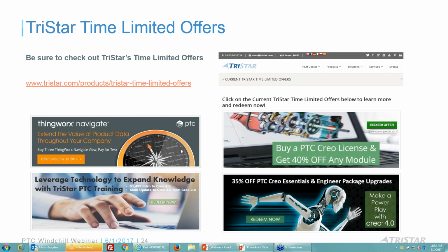Another question was, is it possible to update the EBOM and have the changes propagate automatically to the MBOM? Typically you don't want to do that. You want to have visibility, but the MBOMs are the ones used in manufacturing. Without some kind of validation or approval, I don't want changes on the design affecting my manufacturing parts, because then ERP users will see a new part number or new rev of that part number pop up, and they'll be wondering, is this a new part I have to manufacture too?